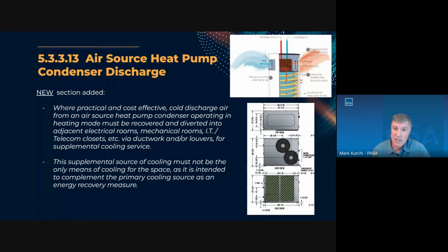So this will mostly apply, especially with our new focus on electrification, to building hot water heaters. With electrification, all hot water heaters that in the past may have been gas-fired, fossil fuel hot water heaters will now have to be heat pumps or electric hot water heaters. And if they're heat pumps, which most likely they will be, because heat pumps will be more efficient than electric hot water heaters, and they're located inside the building, the room that the heat pump is located in will get cold because the hot water heat pump will discharge cold air.